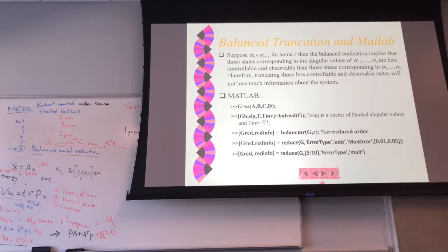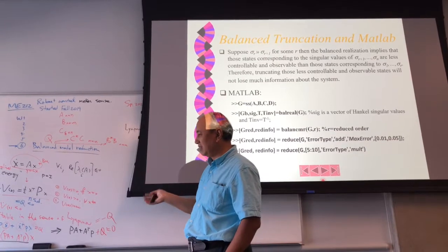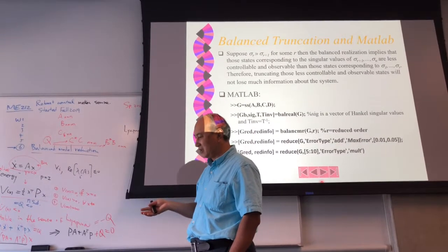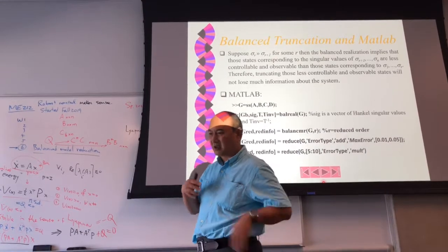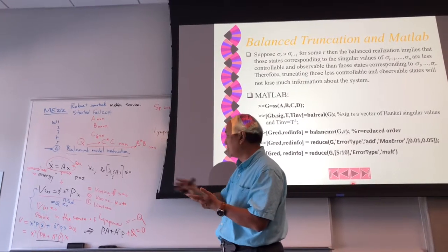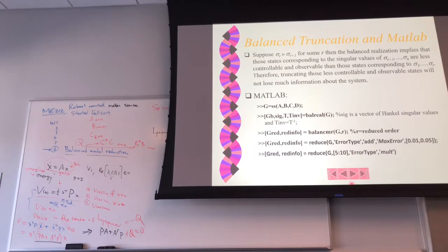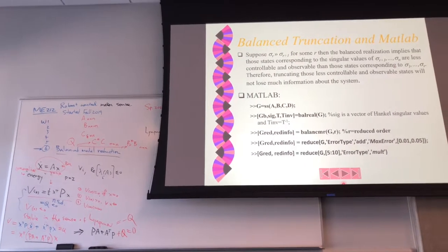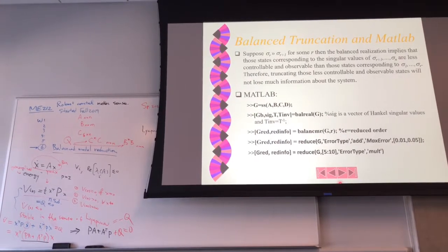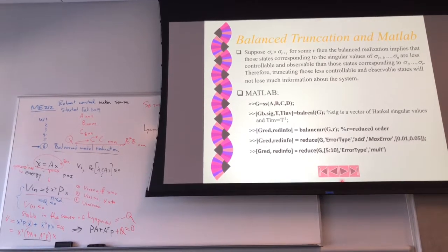And that's exactly we are saying that when you truncate, you're locked into the uncertainty, then we focus on our robust control design so that the robust control will guarantee my performance and stability are robust with respect to those truncated ones, then life is easy, right? So that's the beauty of robust control. And this is also beautiful that give you very solid foundation of truncating or reducing the model order with peace of mind. You have exact knowledge about how much you truncate.